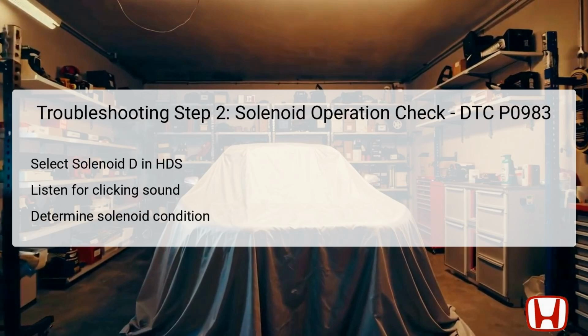In this second troubleshooting step, the operation of Shift Solenoid Valve D needs to be assessed using the HDS. Access the miscellaneous test menu on the diagnostic tool and select Shift Solenoid Valve D for testing. Listen carefully for a clicking sound during the test. This audible feedback indicates that the solenoid is functioning as expected and receiving electrical signals. If a clicking sound is present, it confirms that Shift Solenoid Valve D is operational and allows you to advance to the next step in diagnosis.